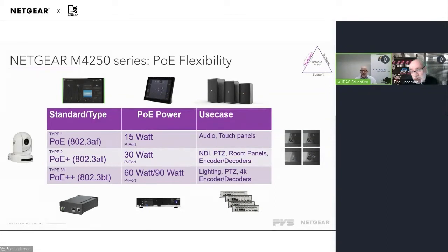Yeah, you don't have to calculate it, because when you stick to the certified cabling, Cat6A for example, and keep to the norm, you will have enough power at the end of the cable of 100 meters.